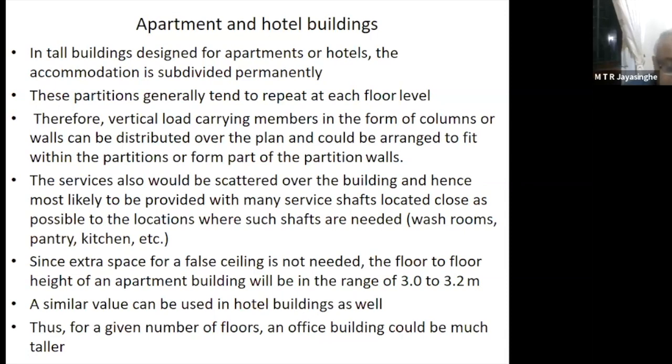And also, the main advantage of pre-stressed concrete is because you are using tendons to carry the loads, the curved parabolic tendons and straight tendons to carry the loads. Whenever you have a concentration of loads, you can always use additional tendons and carry those extra loads to the supports or to the columns. So there are so many advantages of pre-stressed concrete slabs. So that's another option you have to take into account.